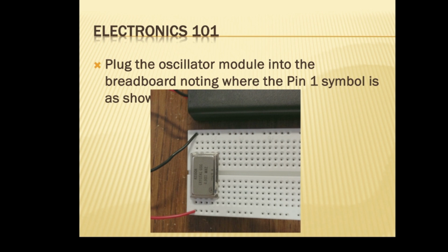But it is not doing it. Oh, we got a bad module. And that's entirely possible. It doesn't matter which lead we hooked up to, because truthfully, I have not checked all these modules. See this black? It's getting a little something out of there, but it's nowhere near what it's supposed to. Black is going to negative. Okay, yeah, and the red is good. And then pin 8 is the signal output, and that's going to positive. Right, it's also ground. Okay, well, okay.